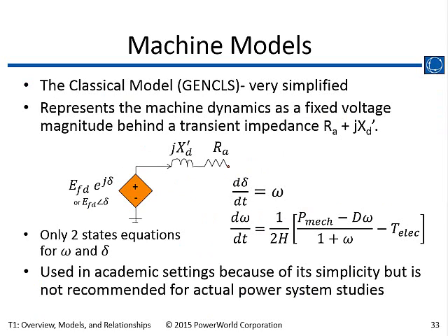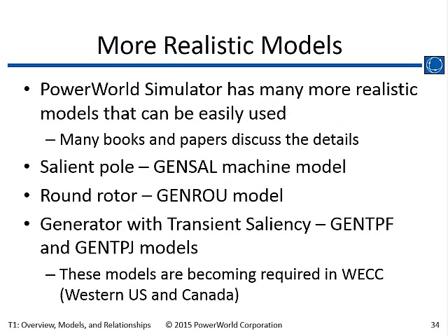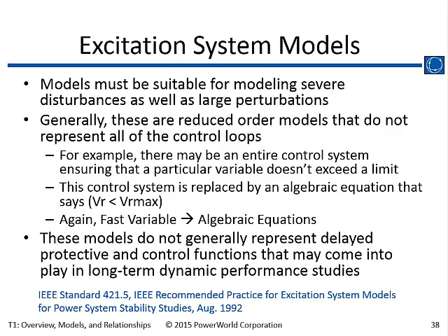Different machine models. The classical model is the one that's talked about in undergrad class, but it's seldom used now in practice. Then you get into more detailed models. I mentioned the GENSAL model, the GENROU model, and then one that's quite popular now in WECC is the GENTPF or the GENTPJ models. So I think they're becoming required in WECC. We get into the details here.